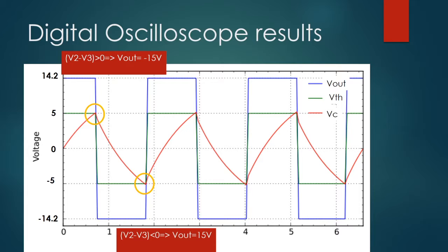Bear in mind that this amplifier has a slew rate, therefore the output signal is not exactly square. The cause of slew rate in this circuit is the rapid change of voltage between the two inputs, which causes a rapid change of voltage at the output in the order of the voltage supply. As a result, the inner capacitance of the amplifier cannot follow such a rapid transition. We can detect slew rate if we zoom in the digital oscilloscope.